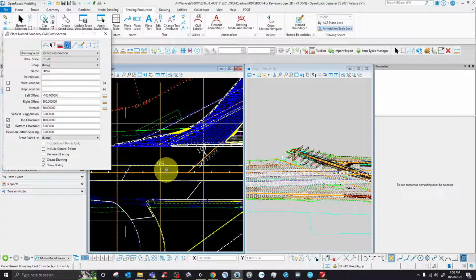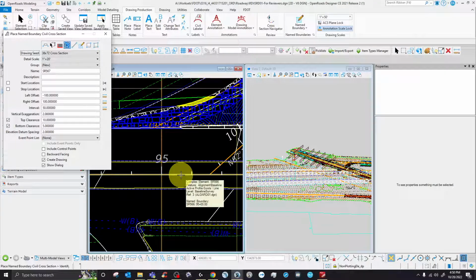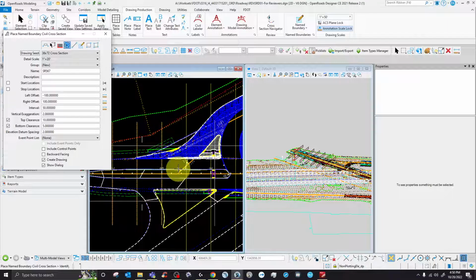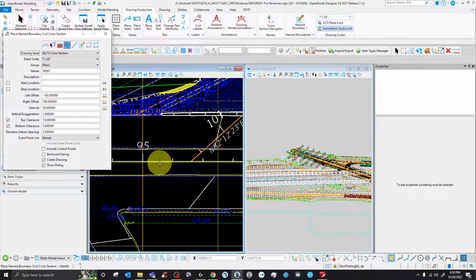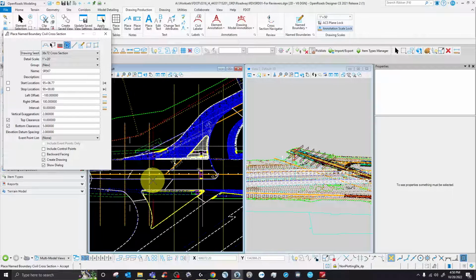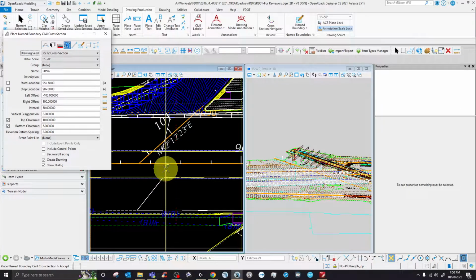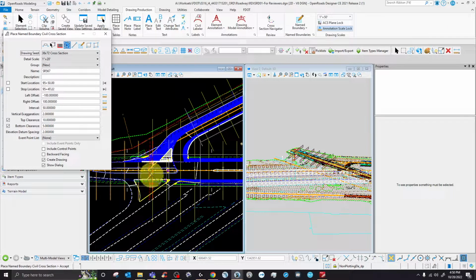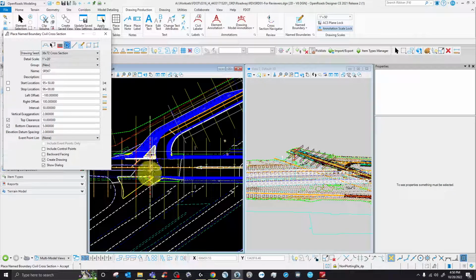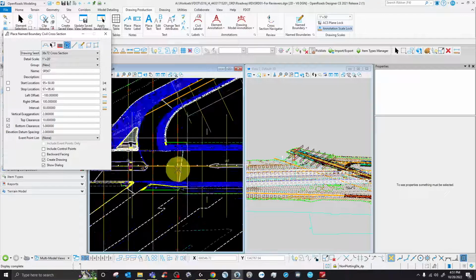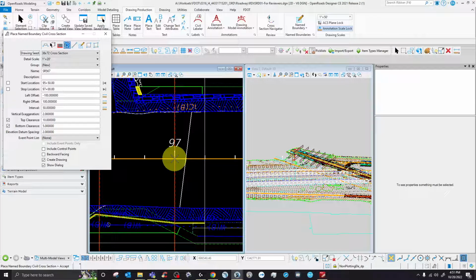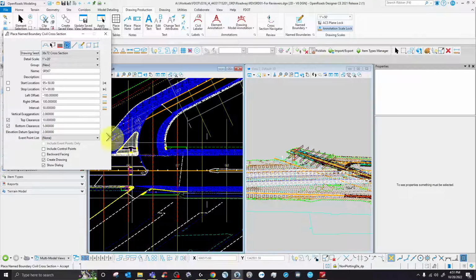So again, let's come here, let's click on the alignment, because this is important. We still just cut in here. We're gonna cut the ramps later on, but for now, let's just click on here. And you see I can move it, but I want it to be here. That's the first one. Because I already made them as 50. And then go here, but I'm not gonna go to this one. I'm actually just gonna stop at station 97. Just one click, and then I have to come here and tell it I want minus 175 and the bottom 175, and then enter.